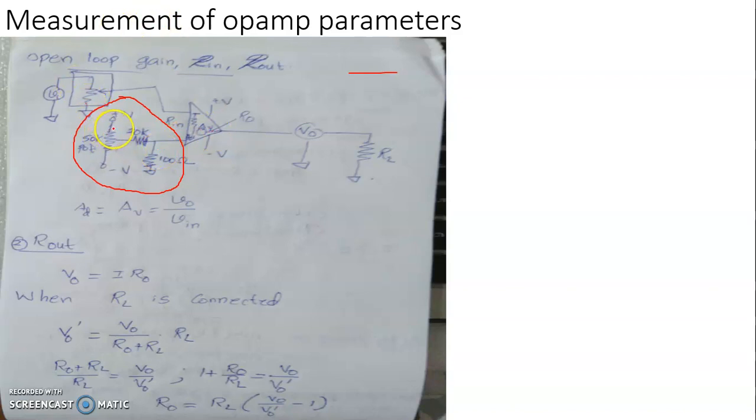That you will have to account for while it is being asked for your examination. So we ascertain universal balancing and we ascertain that the signal strength can be very small with 0 noise level. For that we will be using a -40 dB attenuator here for the function generator or signal source.